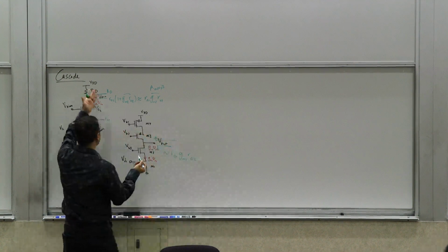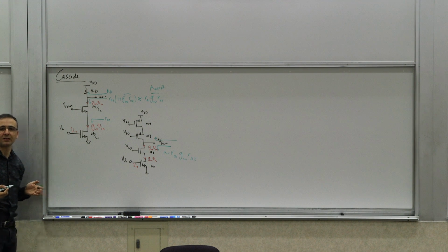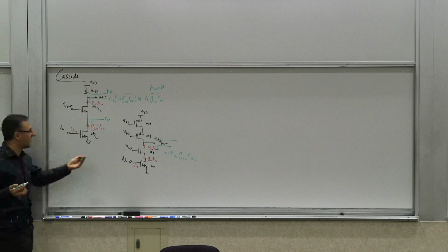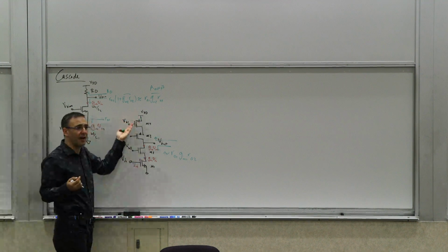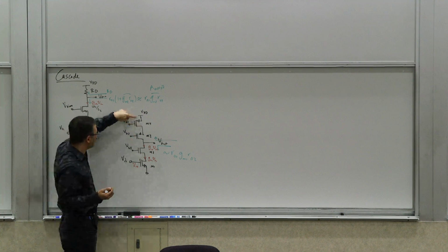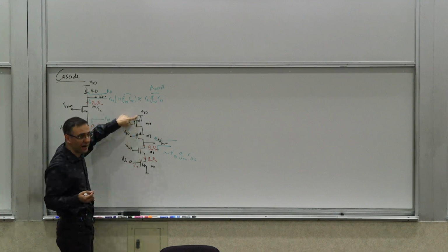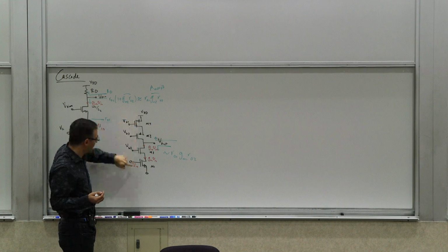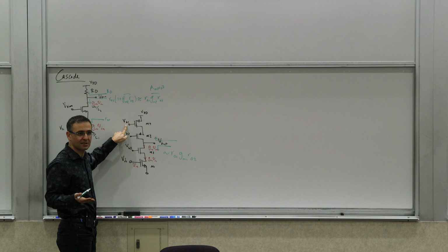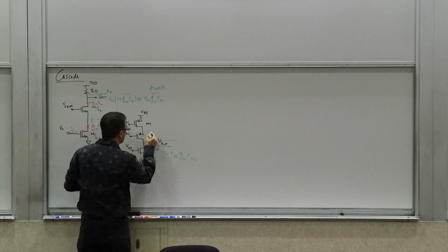Now it's not RD because we've replaced RD with something else. What is it? Well, it's a similar thing. It's a similar Cascode, just upside down, because the source of this transistor is AC ground. It's like the Cascode except for the fact that its input is not changing. But it's the same deal. So what do you see looking into here?